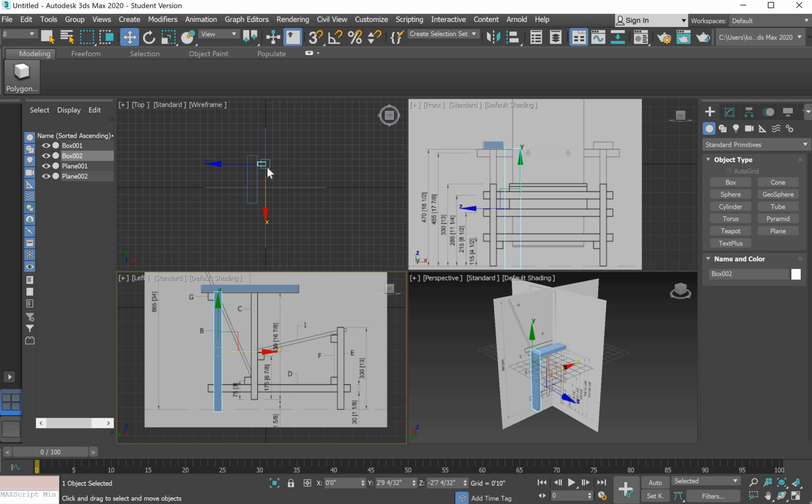It looks like we need to move it over a little bit, and since you can't see the full solid filled shape in the front elevation, that means it's behind, so you can still see it change size, but you're going to have to actually move it within the top or plane view, or this first quad. So by having your move tool selected, just select that box we just drew and move it along the x-axis and see it line up within the front elevation. Okay, so that looks pretty lined up.